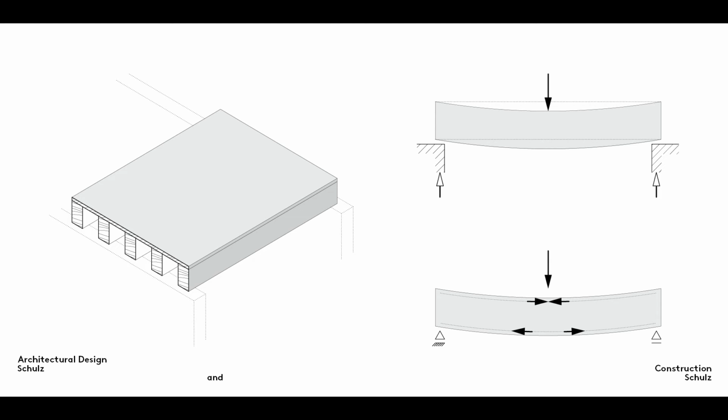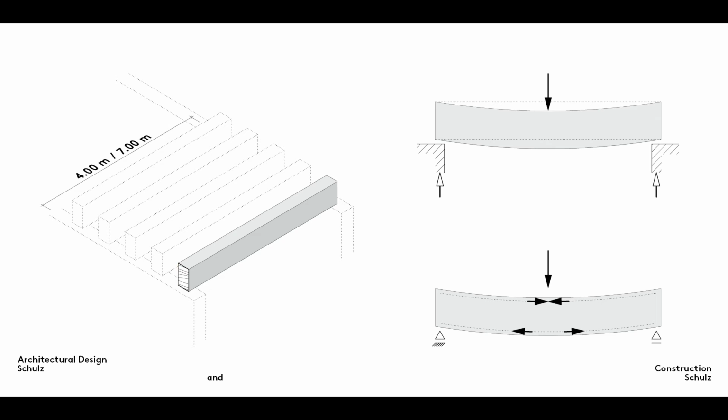This is what a timber joist floor looks like. The timber joists are placed close together because the boards or wood composite sheeting laid over them can only be used for short span widths. While concrete and steel beams have a width-to-height ratio of 1:1 and may even be wider than they are deep, timber joists always have a rectangular cross-section and are laid on their shorter side. As a result, and unlike reinforced concrete and steel beams, the section of timber joist is not structurally optimized. Now let us take a closer look at a timber joist floor.